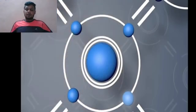So silicon boules are fabricated in a range of different diameters. The most common sizes are 150, 200, and 300 millimeters. Wafers with large diameters offer more space for chips. Extremely thin wafers are then cut from the silicon boules using a special sawing technique. These wafers are the basic building blocks for the subsequent chip production.